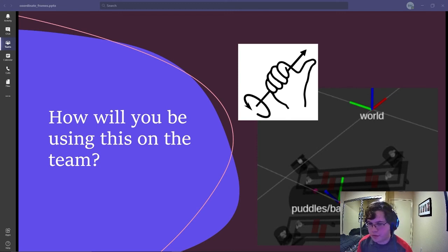The pitch looks pretty much 0, so the pitch is 0, and then finally our roll, it has been rolled to the right a little bit, which is a roll around the x-axis by probably about 10 degrees. And then finally that will give us our orientation here. Yaw of negative 45, pitch of 0, roll of about 20 degrees. So that is how we tell the control system to move the robot to a specific pose.